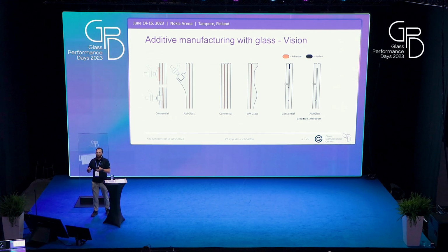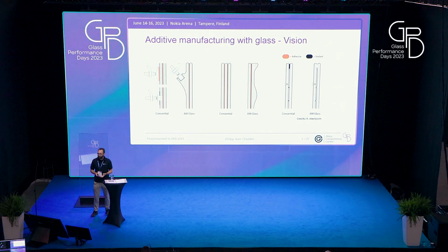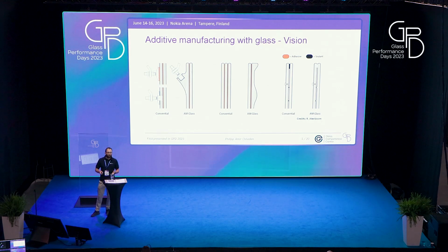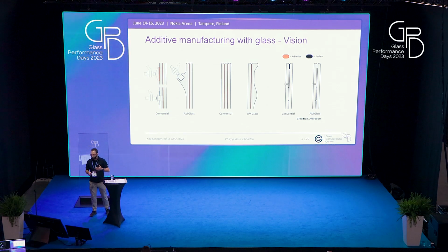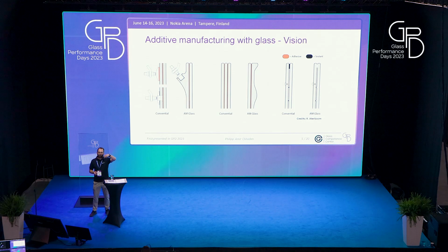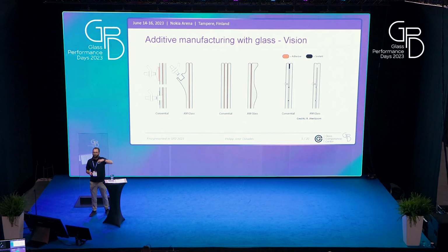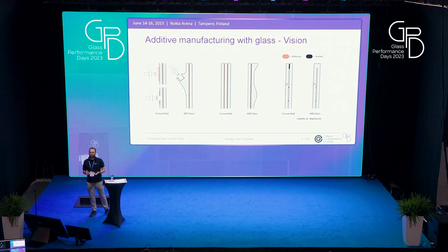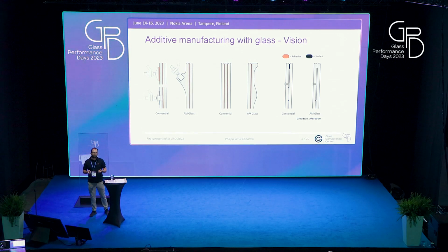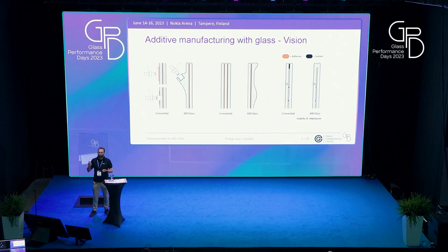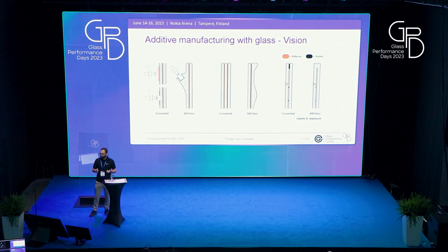With this, we could reduce the total amount of glass needed, just as an idea. Another idea, for vacuum insulated glazing, is that the spacers could also be printed dots out of glass. And since VIGs need a stiff edge sealant, you could also think about trying to fuse those two glass plates on the edge with glass onto each other.